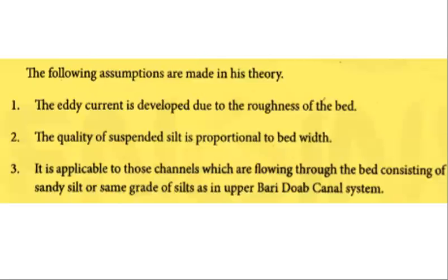So these are the assumptions which are made for the theory. The eddy current is developed due to the roughness of the bed, and the quantity of suspended silt is proportional to the bed width, and it is applicable to those channels which are flowing through a bed consisting of sandy silt or some grade of silt, such as the Upper Bari Doab canal system.